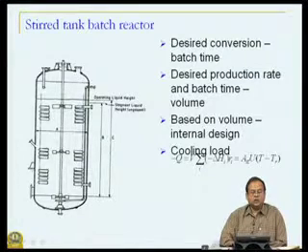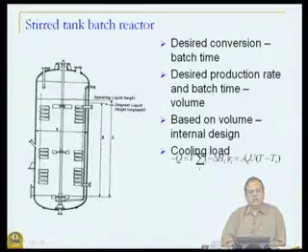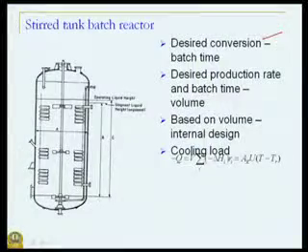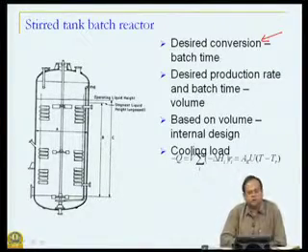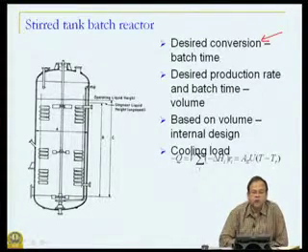So, as we saw in these results, there were two aspects which came out, that you do not want the conversion to go to 100%. So, you have a certain desired conversion in mind. With our model on hand, we can now simulate this process and look at what is the time that is required to achieve the desired conversion, and that will fix our batch time.